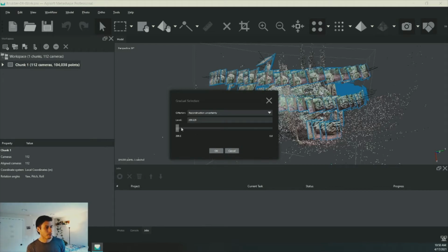is this is going to select based on what level I choose. It's going to select points that it's not totally sure on. So if it has a few points that only have a little bit of surety, it only generated those points based on maybe 2 photos versus 5 photos. It's not going to know if it's totally accurate. It's kind of guessing. A lot of it producing these points for the sparse cloud are just kind of guessing where the points should go.